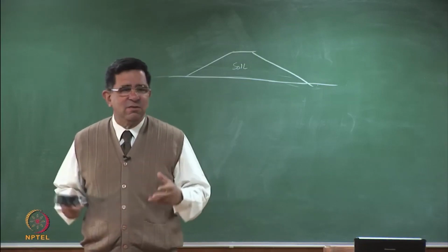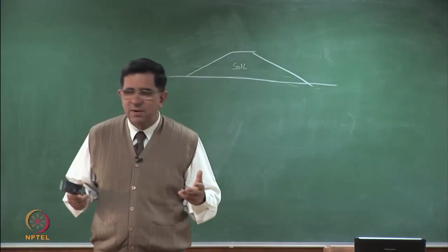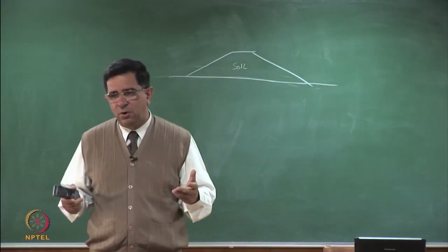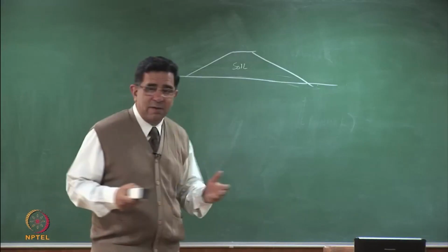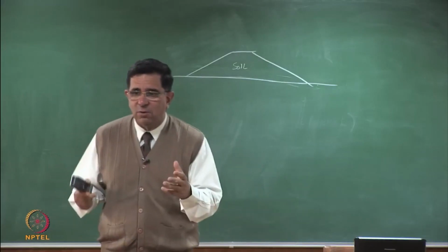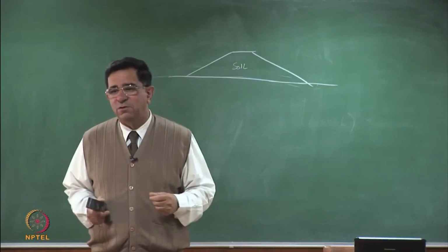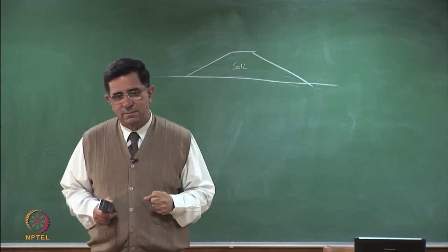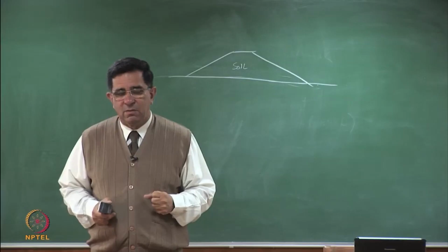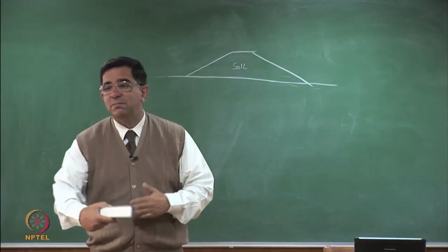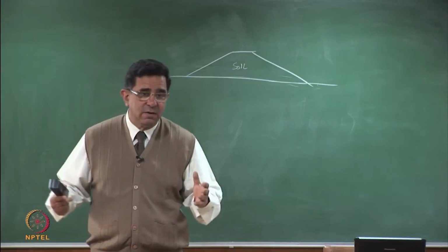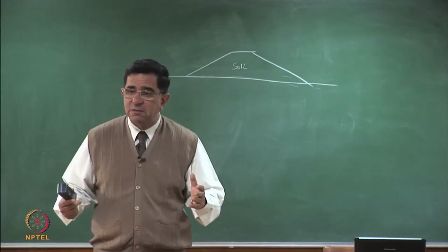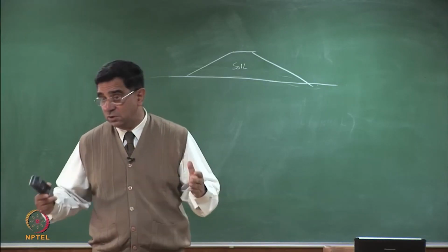Well, it depends on the size of the largest particle. When we are doing testing for dams for rock fill material, when I use the word zone dam, the shell could be made of rock fill. What kind of large size boxes do we need? Well, 1 foot by 1 foot may not be enough, it depends on the size of your rock fill, but you could have 600 millimeters by 600 millimeters or even larger.